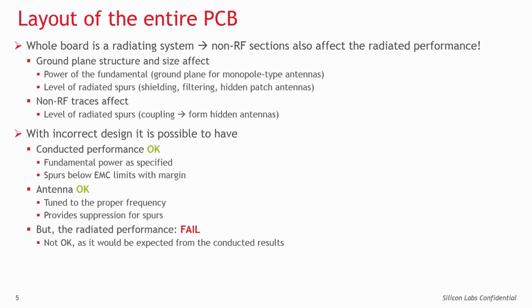fundamental and higher harmonics or spurs compared to the values expected based on the conducted output spectrum and the gain of the used antenna. Incorrect layout can cause the radiated spurs to violate the relevant EMC regulation even if the conducted spurs are below the limit with nice margins. Although in most cases the reference designs are not complete applications, the RF layout design principles introduced in them should be applied for the whole PCB area containing the RF section or module.